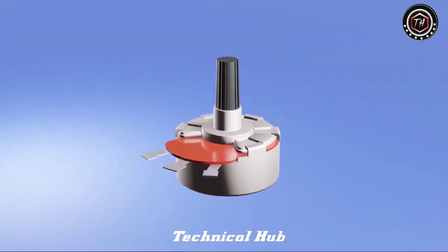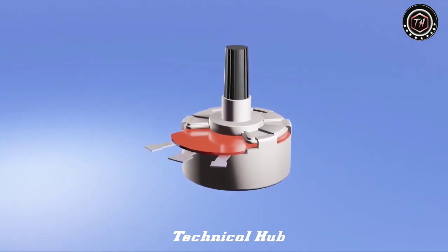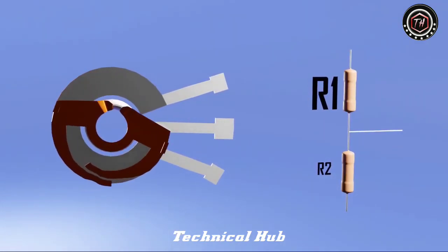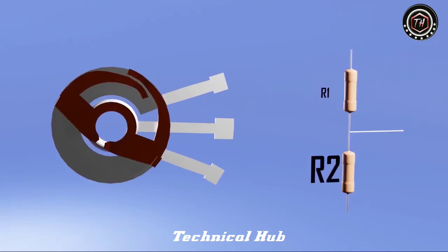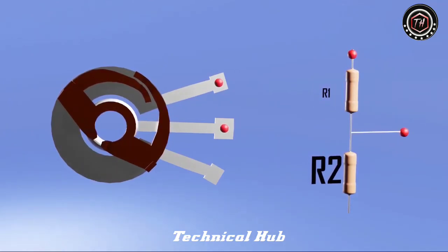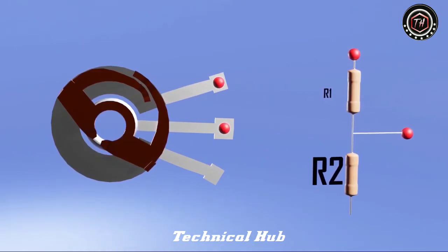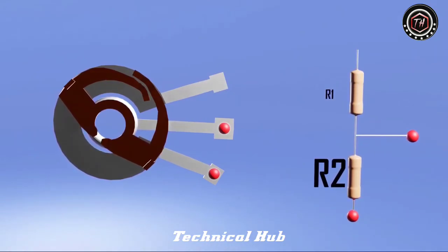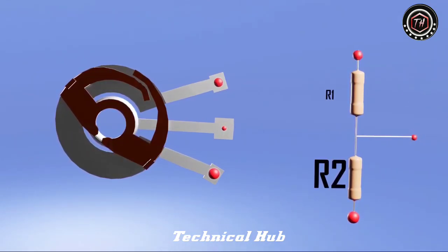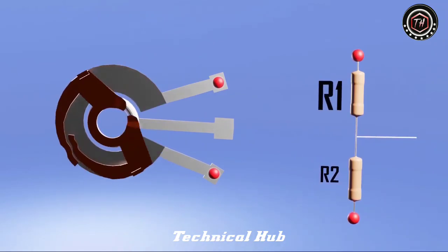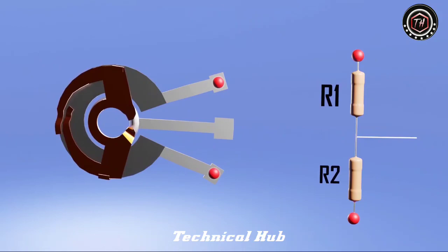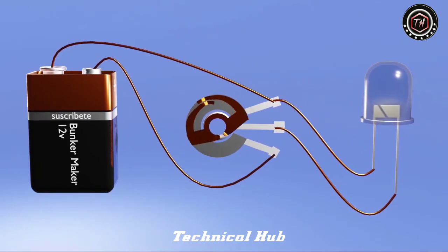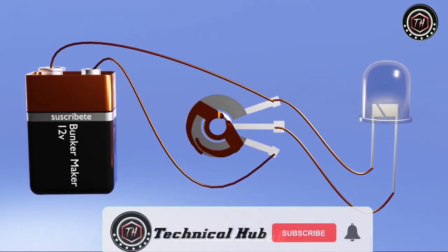The way a potentiometer works is using an arc-shaped resistor, which, by adding a point of contact with another terminal right between its ends, acts as if it had two resistors in series. In this way, if we measure the resistance between the first terminal and the intermediate one, we will obtain a value. Whereas if we measure the third terminal and the intermediate, we will obtain another value. However, by measuring the resistance between the first terminal and the last, this will always be the same, since they are in series. This feature allows us to generate circuits like this, in which when changing the potentiometer we vary the voltage that passes through the LED.